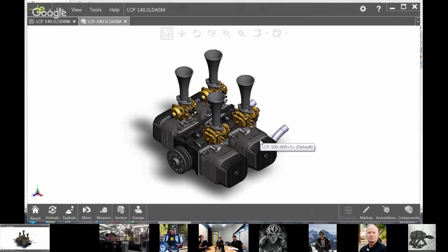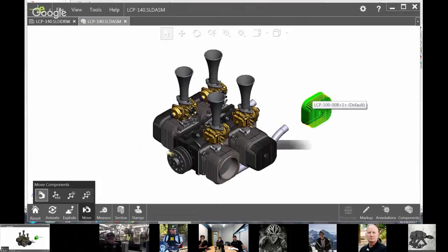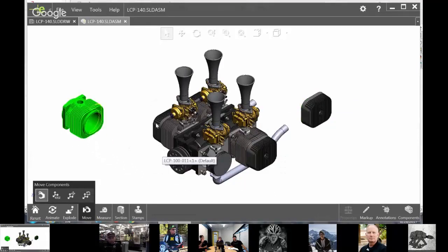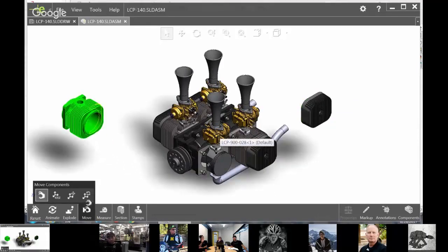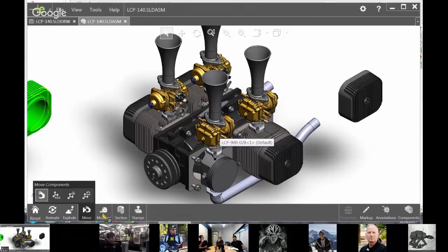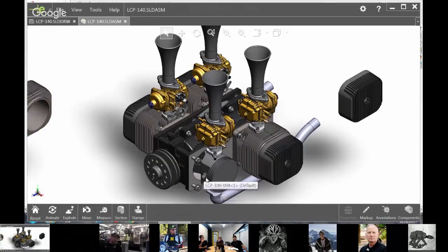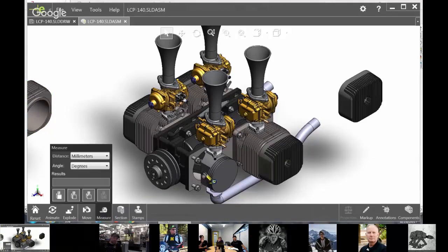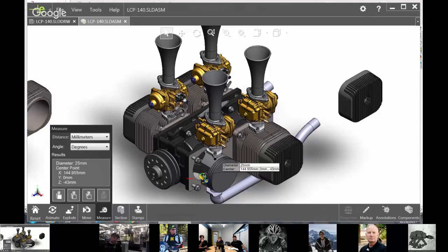When you open up an assembly in eDrawings, you can go into the parts and just start moving pieces around if you need to get inside the assembly. So again, if all I needed to do was go in and find out how big this was, rather than sitting there spinning my wheels trying to get this assembly fixed, I can go into eDrawings, open the thing up, take the measurement, get out of there, I'm done.